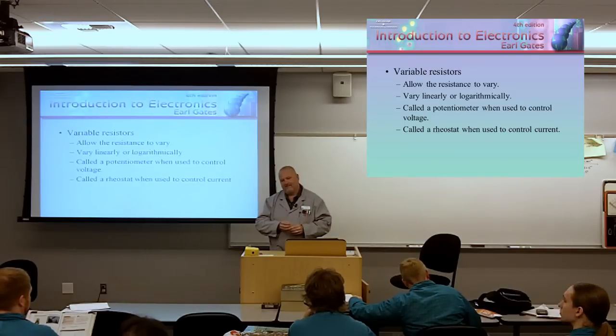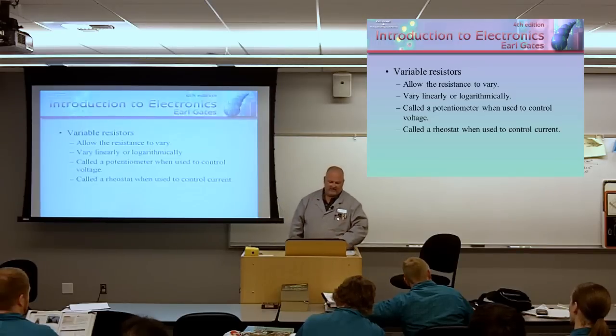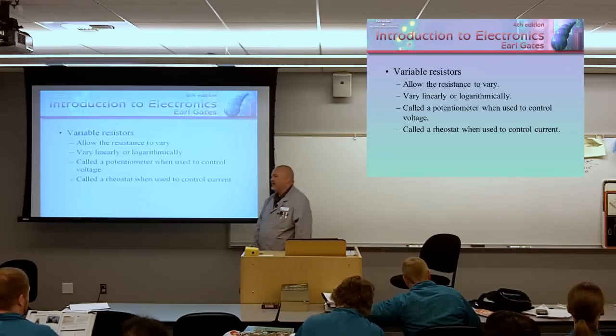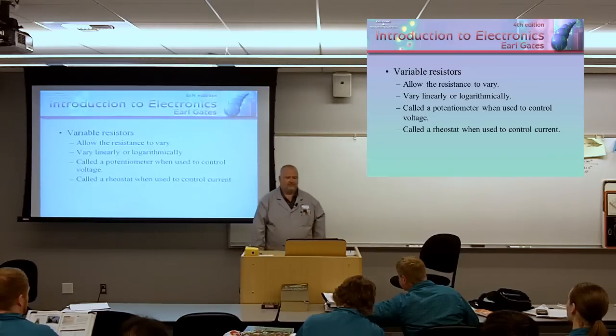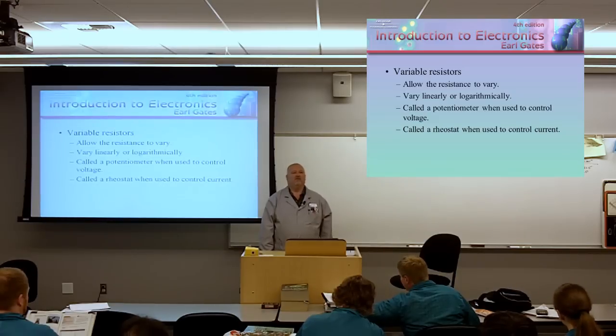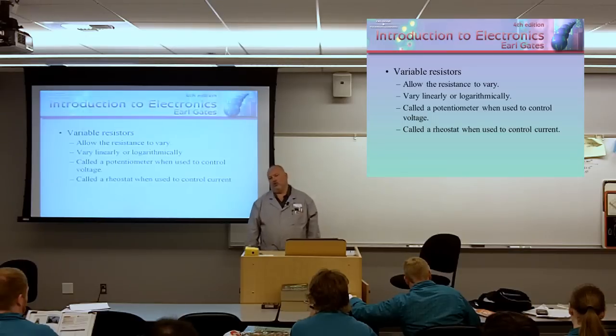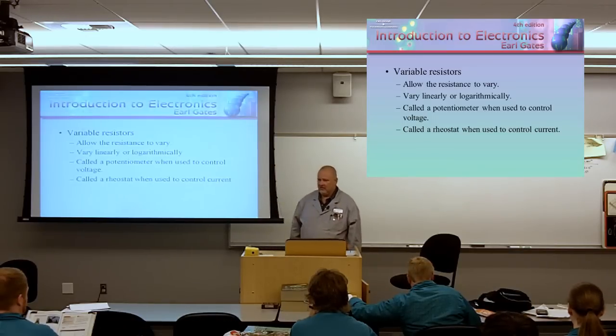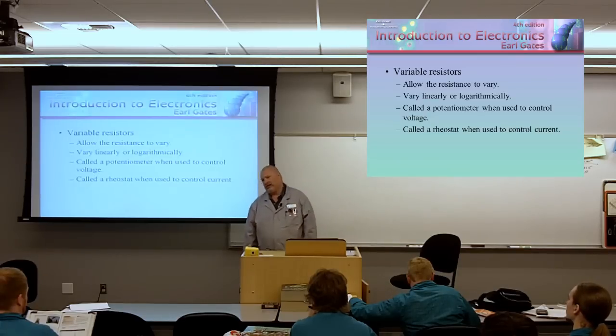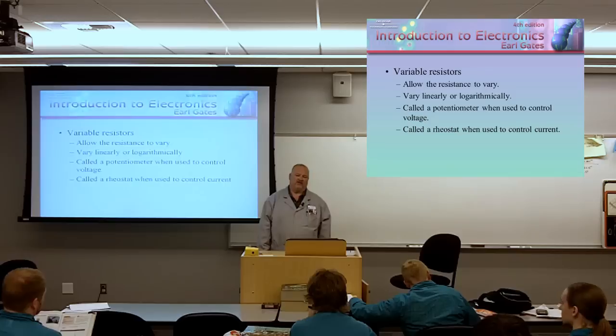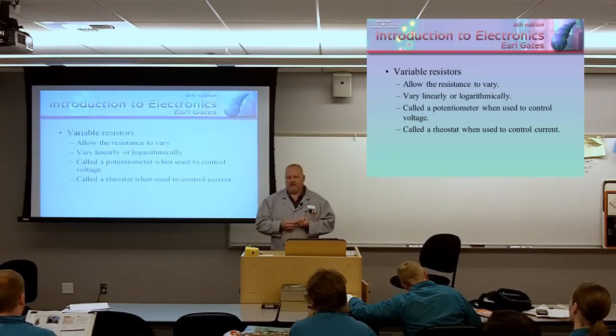Isn't it mainly with audio? Very good. To do with audio. Logarithmic is used for audio applications because audio is not linear. Audio, some of you may be aware, is measured in decibels, and that's on a logarithmic scale. So if you want to control something that is nonlinear, you need to use a control that's nonlinear, and audio is that example. So that's why we have this logarithmic control.